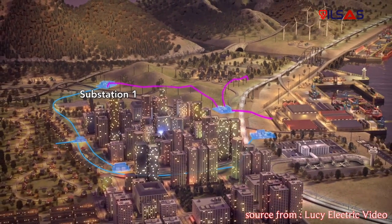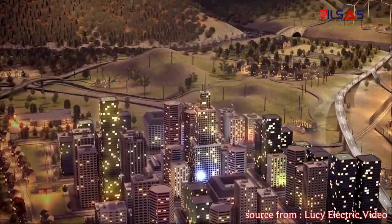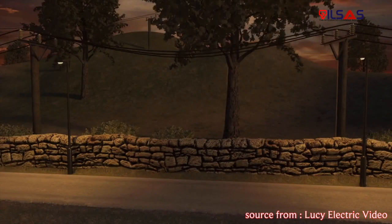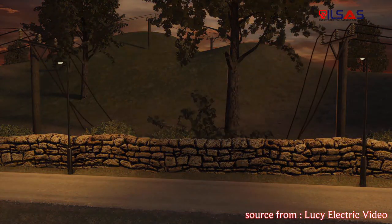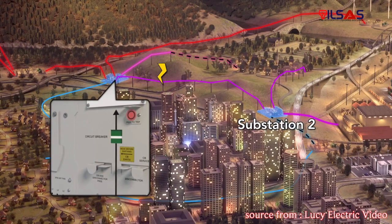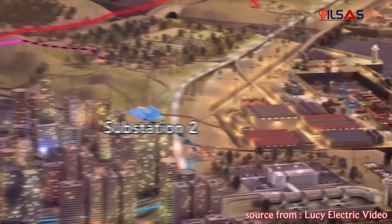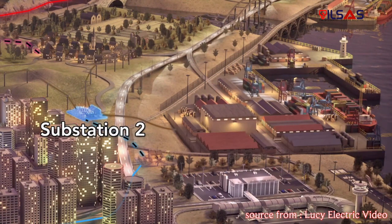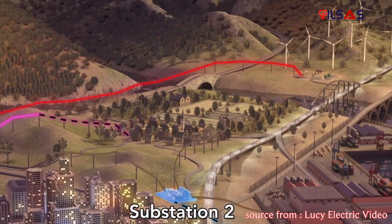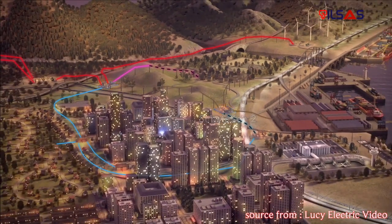Let's see how the Scada system is used to manage and maintain the network during a fault. On a remote rural section of the network, a fallen branch causes damage to the overhead power lines feeding substation 2. This break in supply causes the circuit breaker for this line to trip at the primary substation, leading to a total power outage to both the port and the rural community that rely on this circuit. Power to the rest of the network remains unaffected.